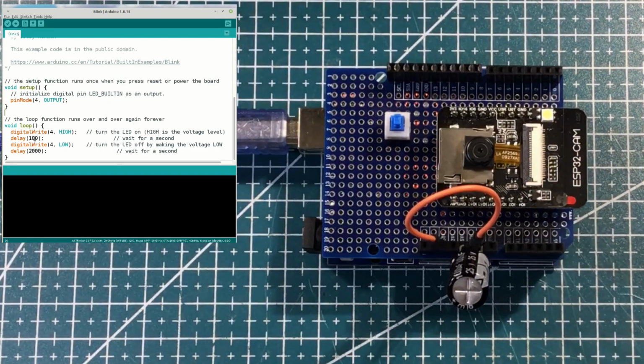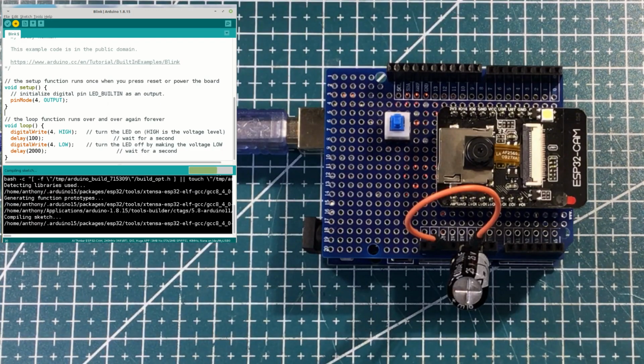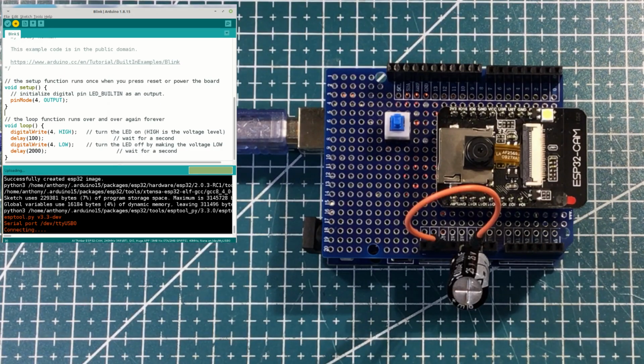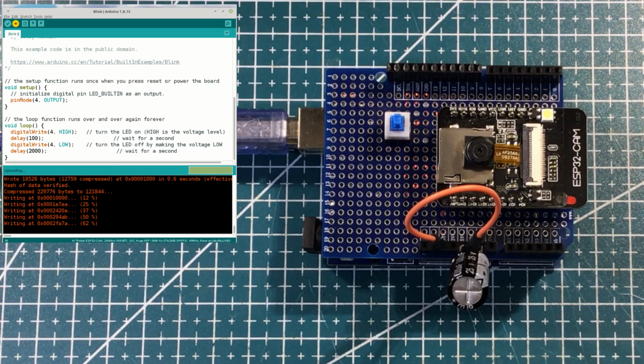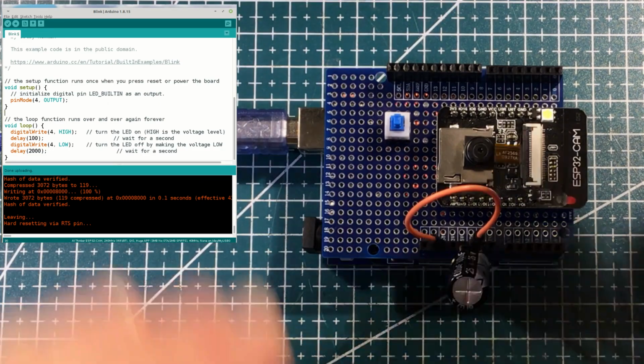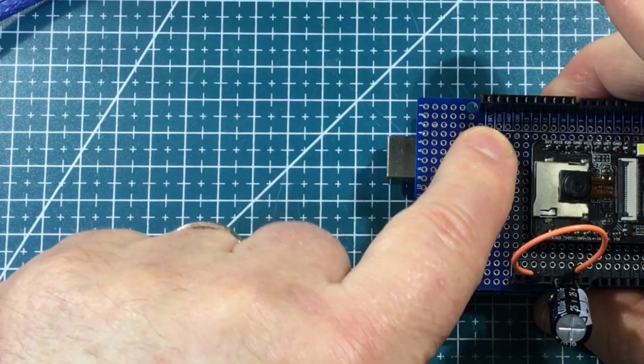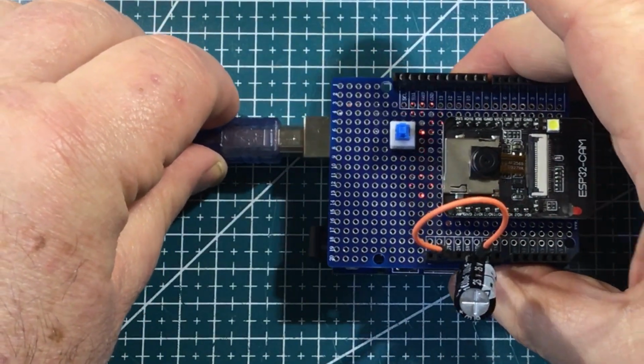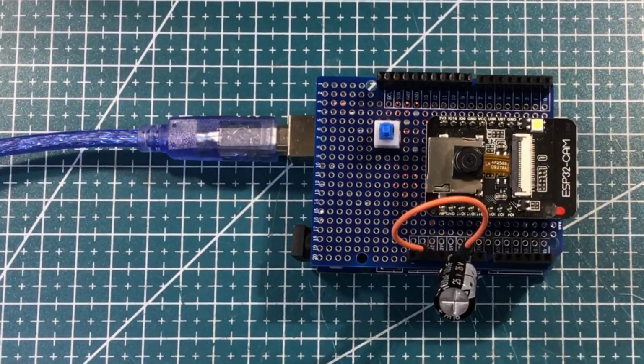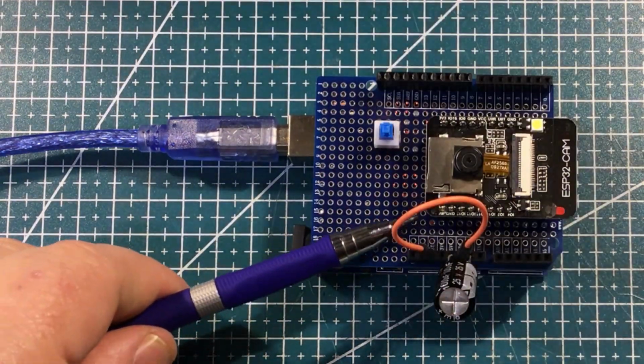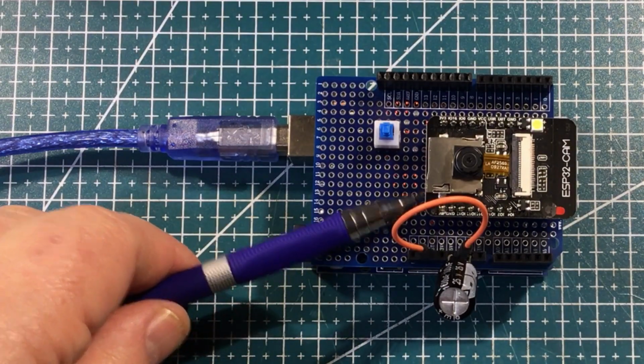All right, so I didn't see that flash, which worries me a little bit. Let's go for a program that maybe has a shorter flash but a longer delay. So we'll go for a 100 millisecond flash, which is a blip, and then we'll go for a 2-second delay. Okay, so it's compiled okay and it's uploaded okay. Alrighty, so back out of programming mode, back in again, and a blip and 2-second delay. Hey, that's pretty good. Now there is actually a reset button underneath, which is a bit awkward to get to.